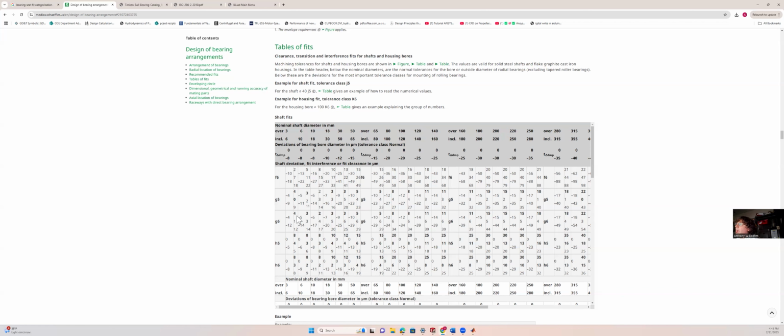And it's saying that at worst case scenario, maximum material condition for both the bearing and the housing, you have 8 thou undersize for the bearing, and you have only 4 thou undersize for the shaft. That would be 8 minus 4, which would give you 4 thousandths interference fit. And that's why it's bold, because it's interference.